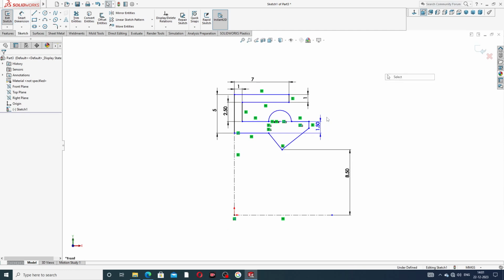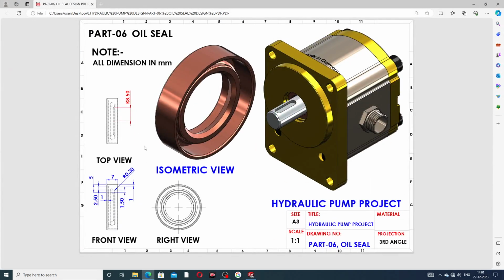And this is this. Okay, drawing this, a distance is 1.5 default, and 2.5 is this, and this is 5 millimeter and 7 millimeter and 1 millimeter, and this is also 1 millimeter, and use a radius, and this center point distance is 8.5 millimeter. Okay, all points are drawn here easily, and use a fillet here, 0.5,